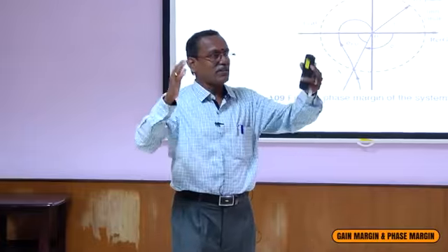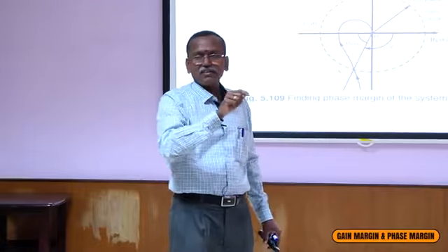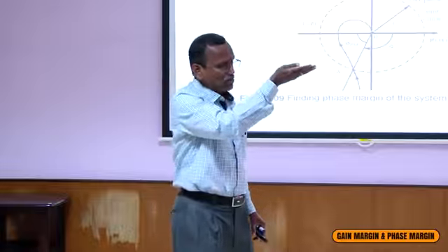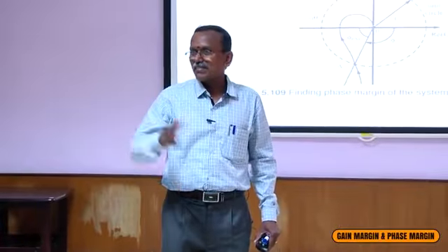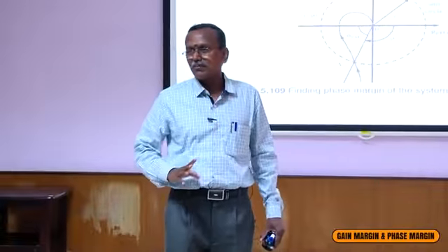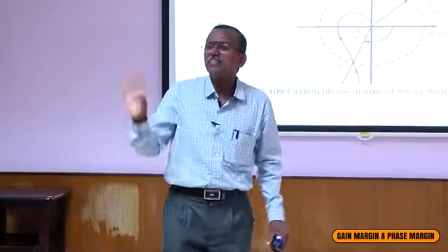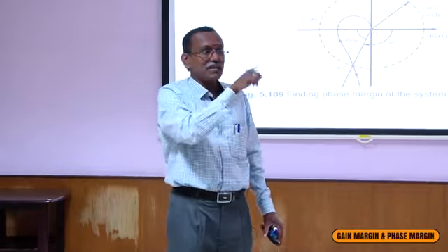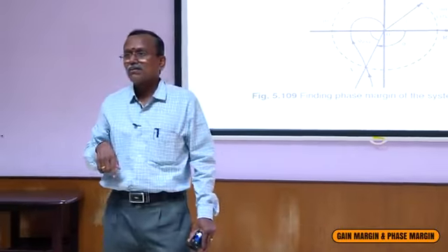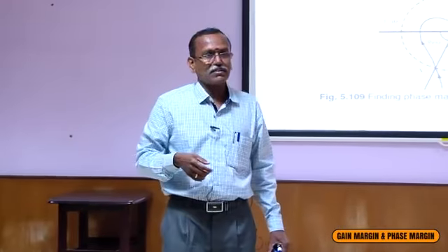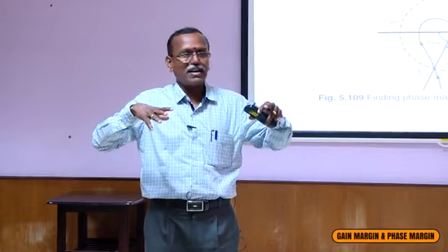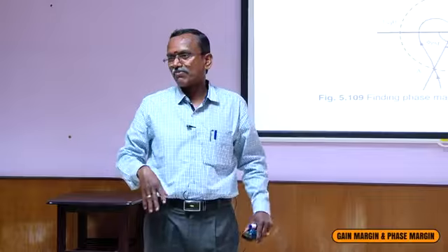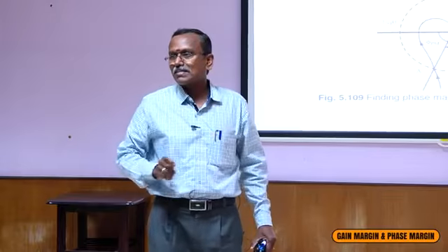They will calculate the dimension, maybe 1/4 or 1/6 of this. I am not a civil engineer. That much pillar size is sufficient for this building, but they constructed it 4 times higher than that. Why? Factor of safety. Even if an unexpected thing happens, it should be strong enough. That's why it is constructed 4 times stronger.